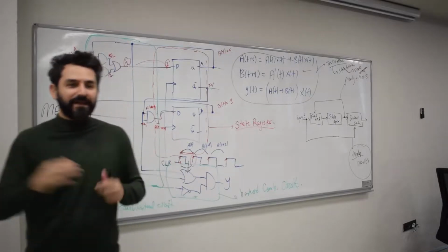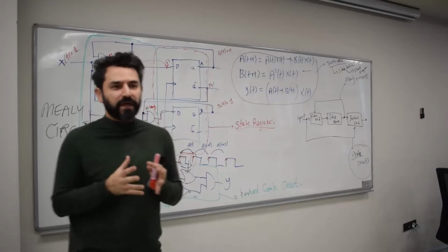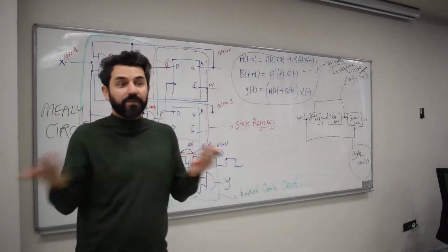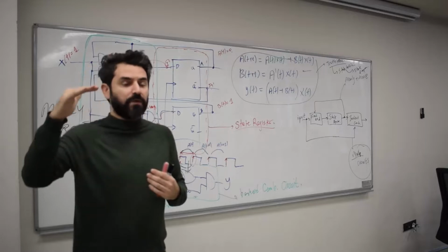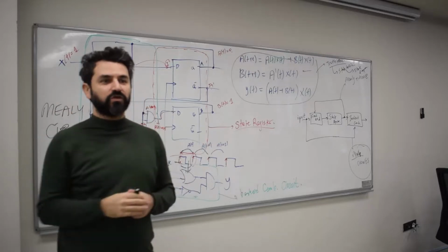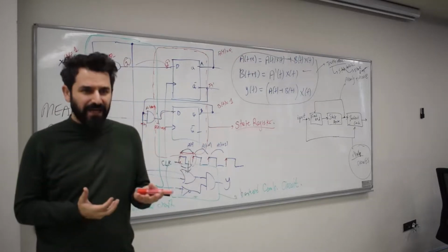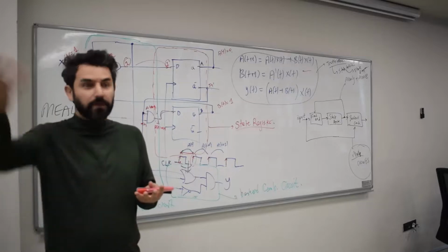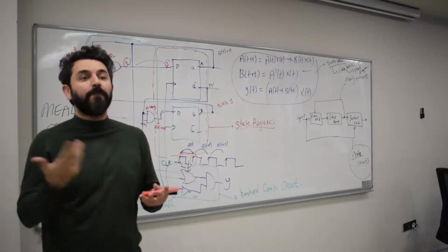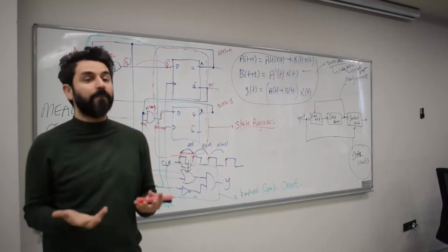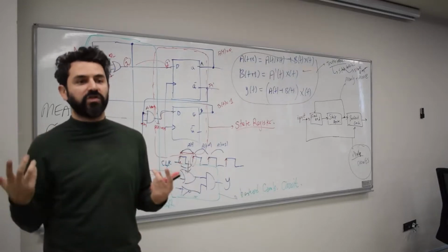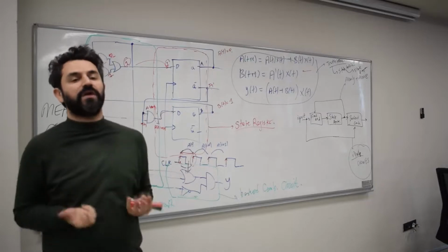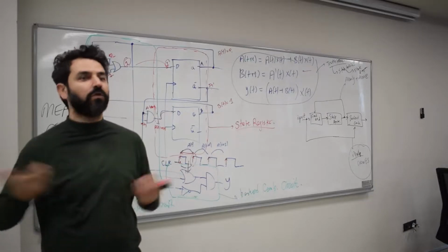So at some point, the receiver will think that the signal may not be coming to me because what I'm seeing is just ones. In other words, 5 volts all the time. The signal is just fixed. So you cannot differentiate whether it's data or because of some problem in the communication channel, it just happens that I'm receiving all the time 1 because of an error in the communication channel. That cannot be differentiated if you send ones all the time.